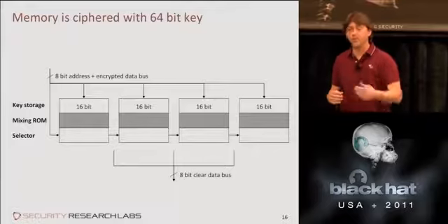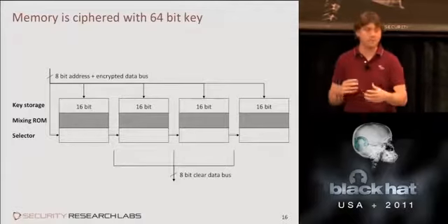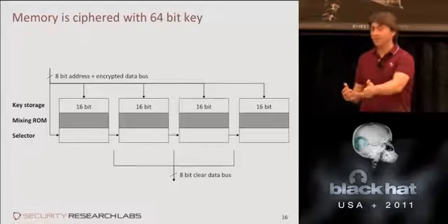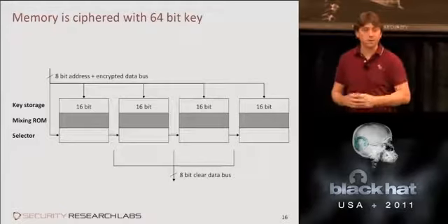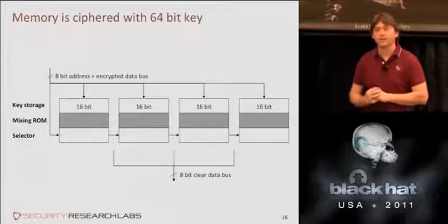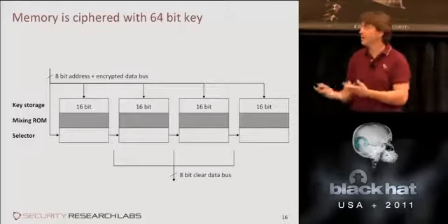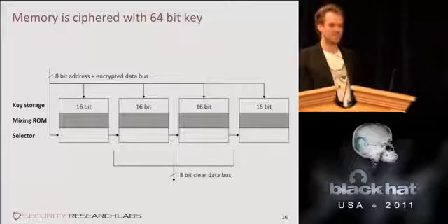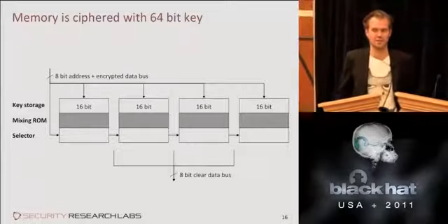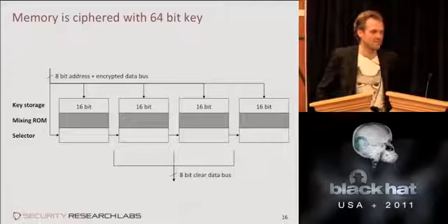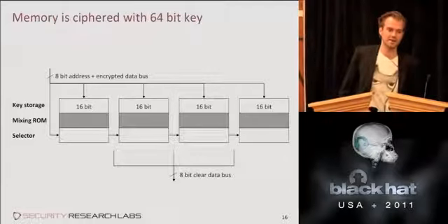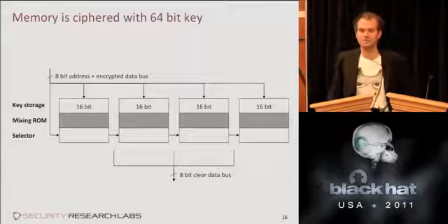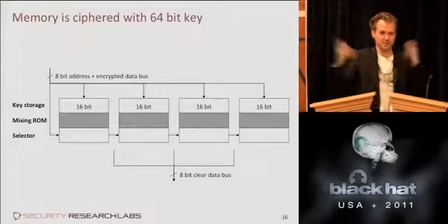So we're dealing specifically with memories we know are encrypted. But even still, like you said, the whole power-up sequence of this chip ran on clear code. The vendor never told you that, and would probably never even admit it. Yeah, so the coverage of this encryption function is fairly limited too, we found. As Chris just said, the beginning of ROM has to be unencrypted, since at the very beginning no keys are loaded into this function yet, so it couldn't decrypt it.